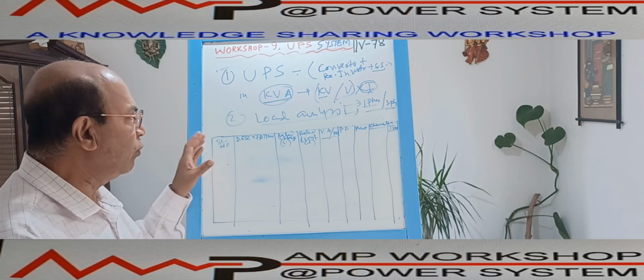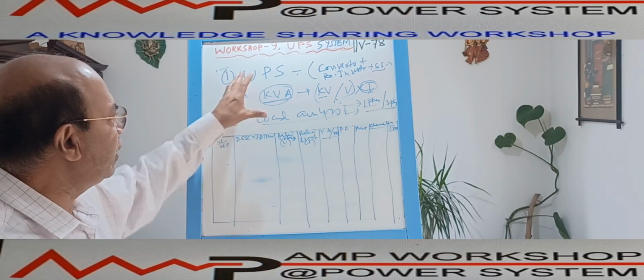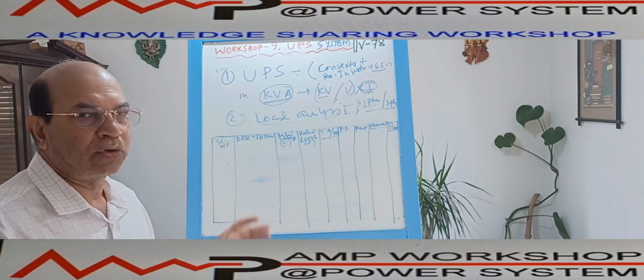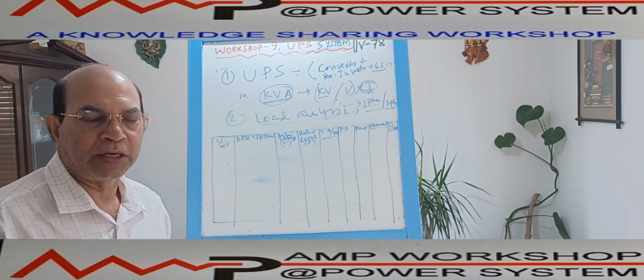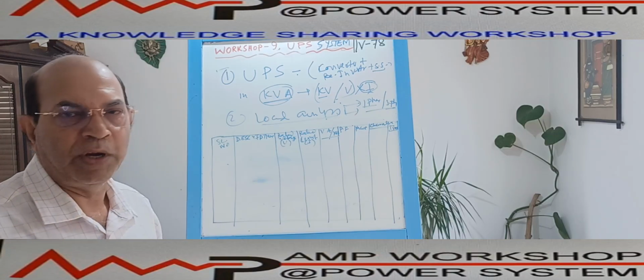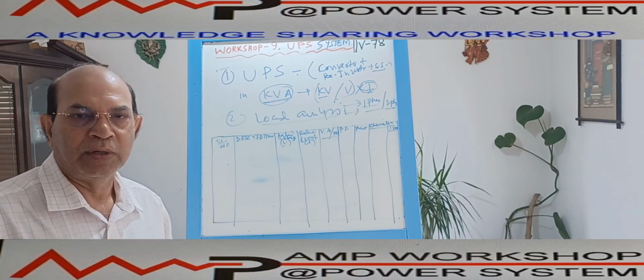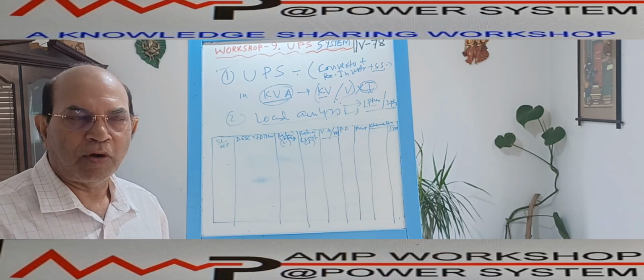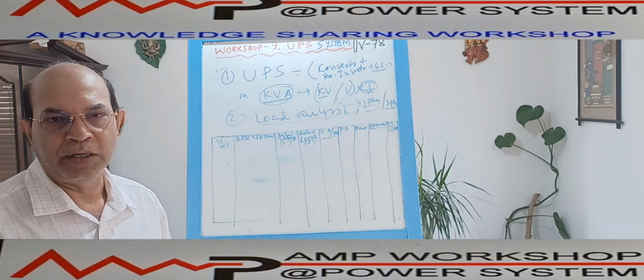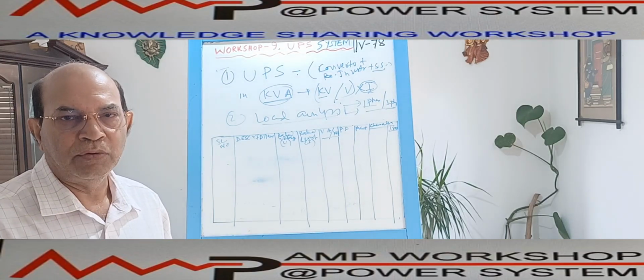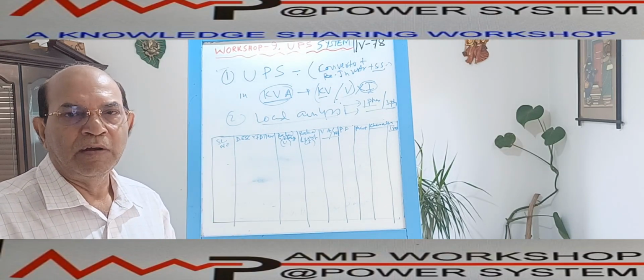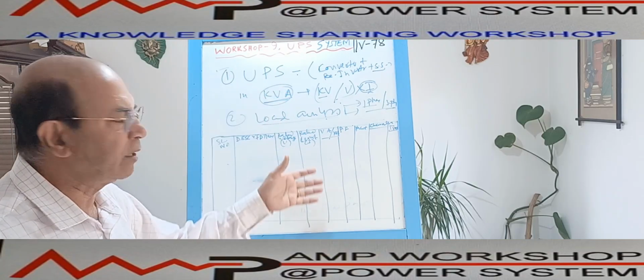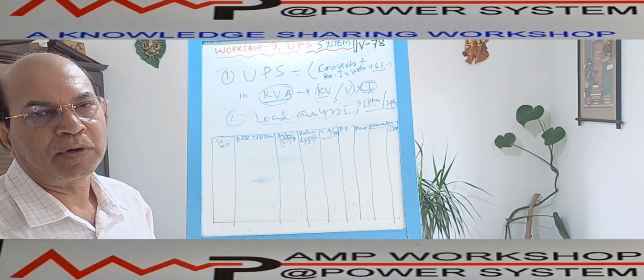So sometimes, though electrical engineers are doing this calculation, some of the loads do not belong to the electrical engineer. Some of the loads belong to the instrument engineers, like fire and gas system load and DCS load. So you have to communicate with your counterpart, the instrument engineer who is working with you on this estimation. From him you have to get all the parameters and then calculate.